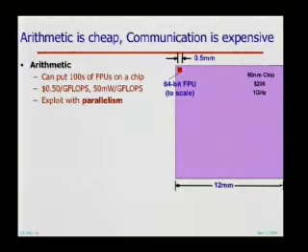So if you look at the amount of die area, and amortize $200 over the die, a gigaflops is 50 cents. You ought to be able to buy a gigaflops for 50 cents. And by the way, it also dissipates about 50 milliwatts going at a gigahertz. So a gigaflops is also 50 milliwatts.